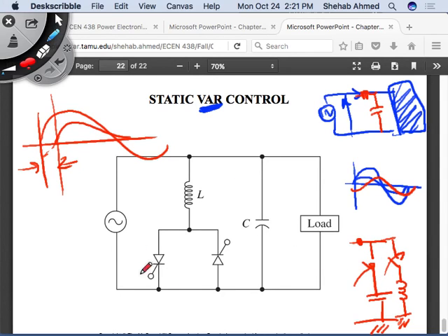The way to do that is with power electronics. So with power electronics, I can put a thyristor looking down, and I can put a thyristor looking up. This way I can control current through this inductor in both directions, right? And I can control it to whatever I want it to be, right? If I apply small alpha, then I'm putting a big voltage across this inductance. Large alpha, large delay angle, then I'm putting only a small voltage across this inductance.